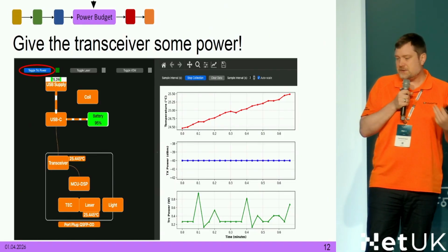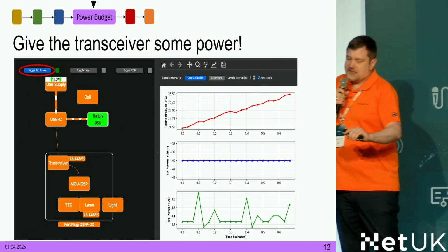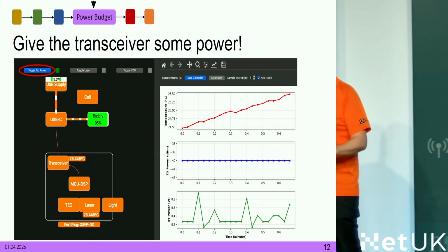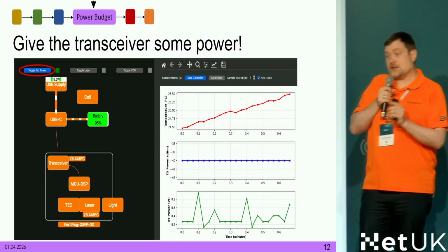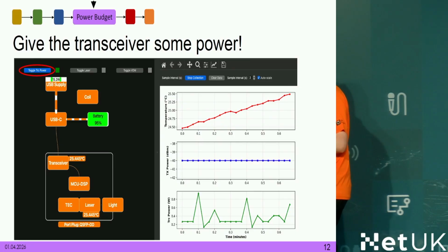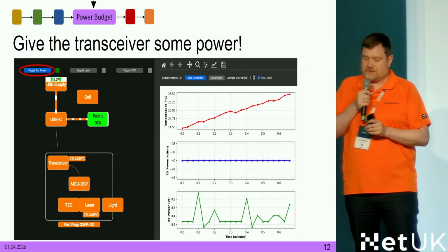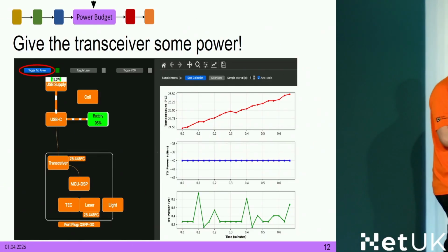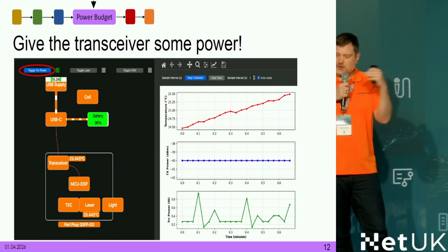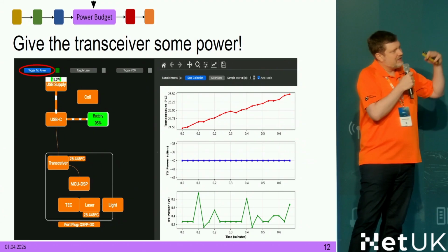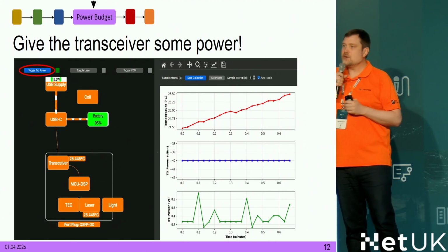Obviously it goes up, it's warming up the transceiver, but it takes power at minus 40 dBm, you don't have a signal yet. And that is a mode where your transceiver is already operating, because in the TRx power, the green curve, you can observe that it's taking very little power, like almost 1 watt, even at the maximum value. That is the so-called low power mode.